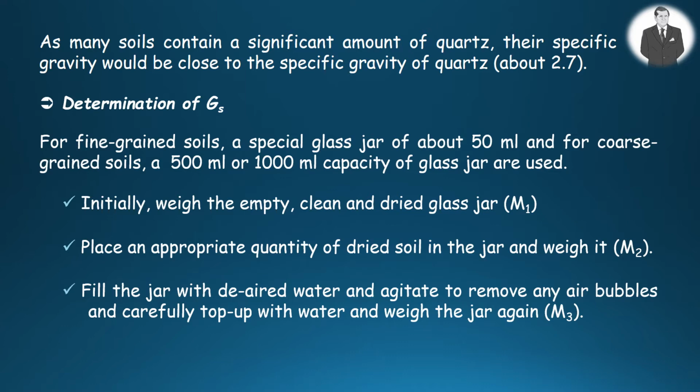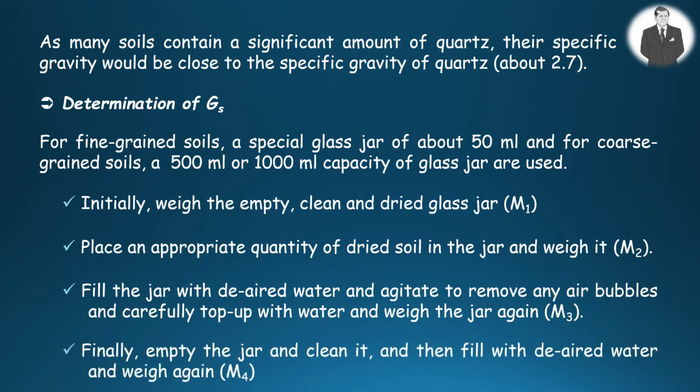The glass jar is filled with de-aired water and shaken to remove any entrapped air bubbles, and carefully topped up with water and weighed again. Finally, the glass jar is emptied and cleaned, and then filled with de-aired water and weighed again.